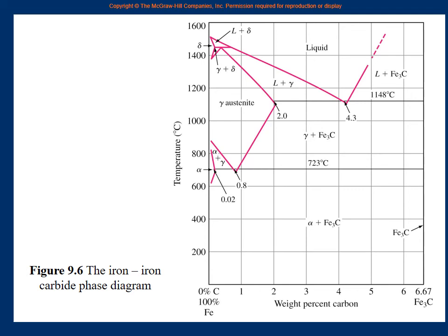Now this point is the eutectic point. Liquid changes to two solids. This is something new: a solid changes to two solids. So they said that this is similar but different. So what name should we give? This is eutectic. This is eutectoid, like eutectic, right? It is a very nice name: if this name is eutectic, liquid to two solids, then a similar reaction of one material into two materials directly, but solid to two solids, let us call it eutectoid.